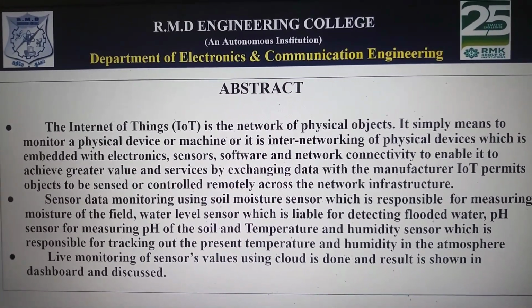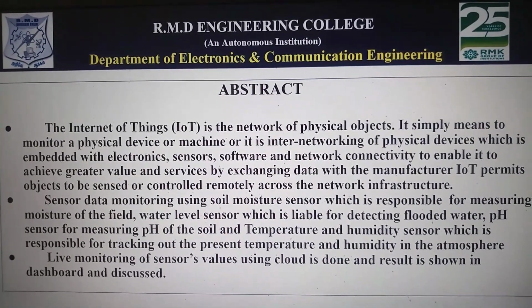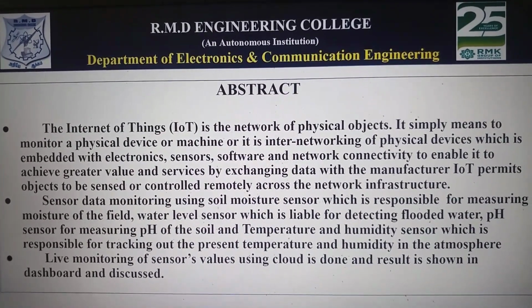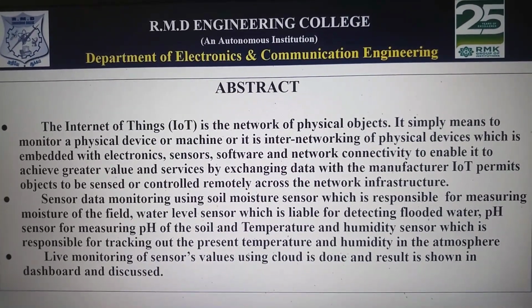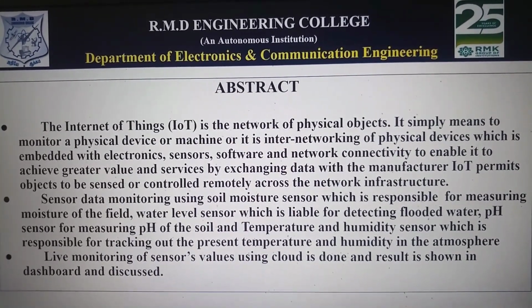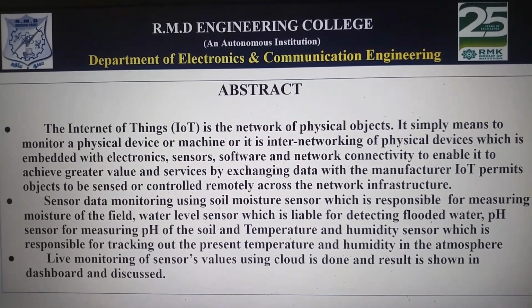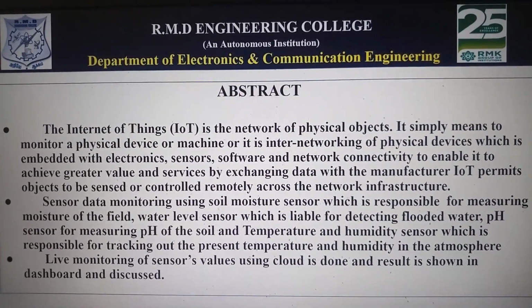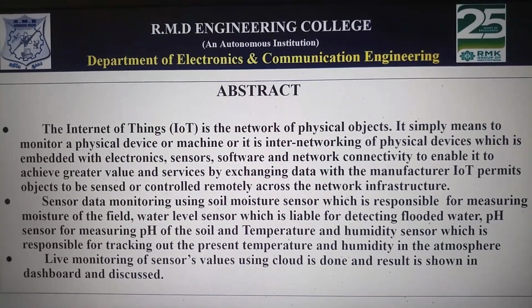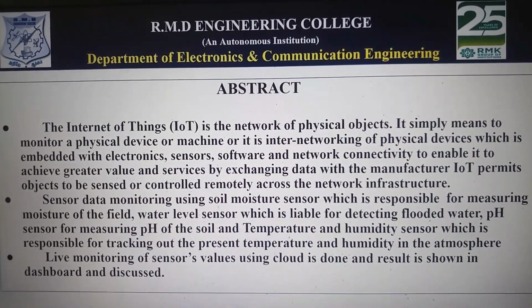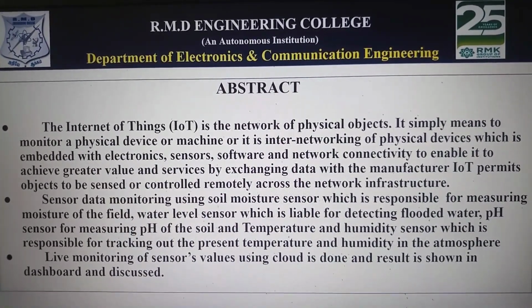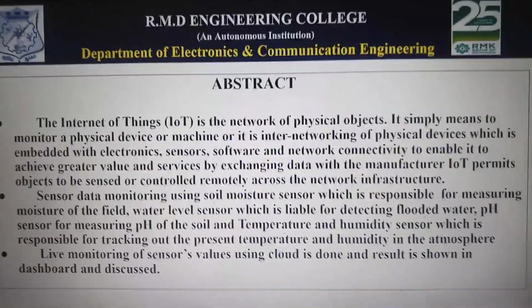So we are trying to demonstrate IoT in plant monitoring. The system monitors and maintains the approximate moisture content in the soil. ESP32 is used as a microcontroller to implement the control unit. The setup uses a temperature sensor, moisture sensor and humidity sensor which measure the appropriate temperature, moisture and humidity in the soil. These values enable the system to use an appropriate quantity of water, which avoids over or under irrigation.